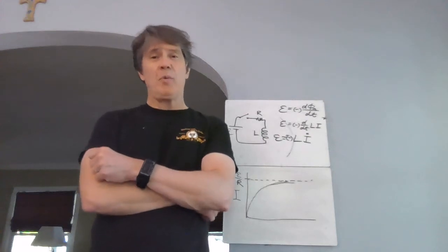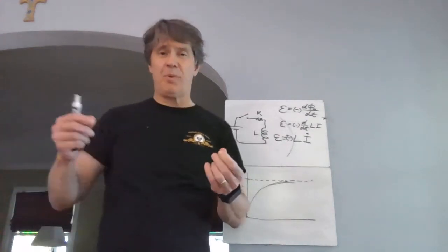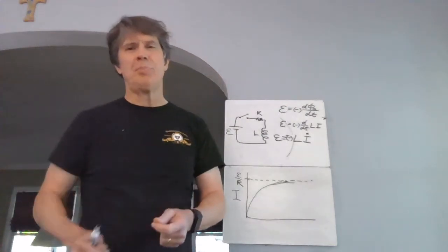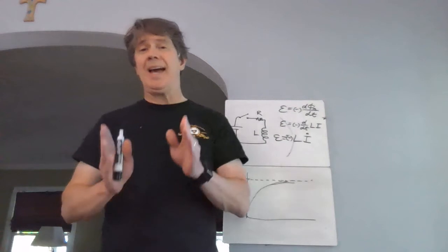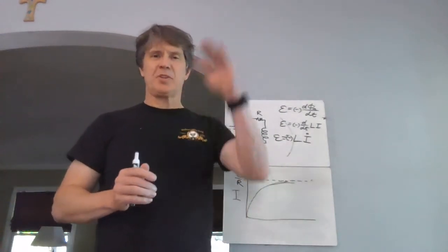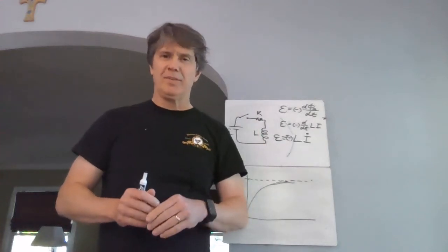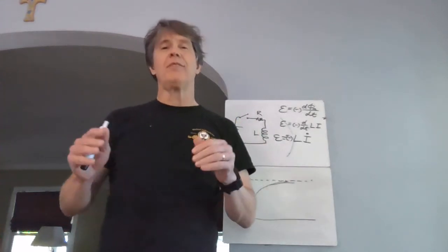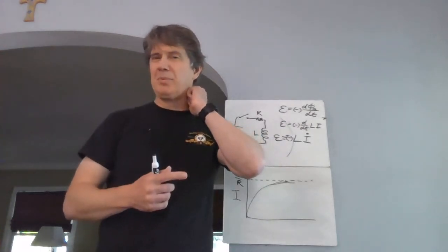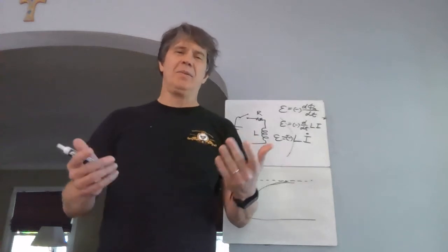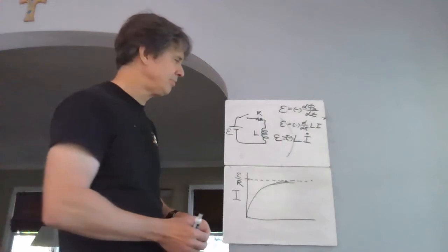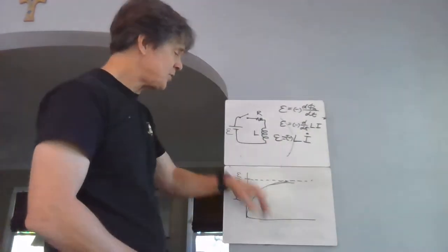So what did I do? I went up on the roof, and I got the wire, the cable, and I wrapped it many, many times around a metal pole, figuring I'm making an inductor. And then when a surge tries to happen and tries to crank the current way up, the inductor goes, no, no, no, no, and it fights back. I don't remember if the problem ever happened again, and then it would get in the radio one, but at least it would try to help. Whether or not it was enough, I don't know. So that's one kind of surge protection sort of thing. There are probably other technologies. In any case, this is what you'd expect.